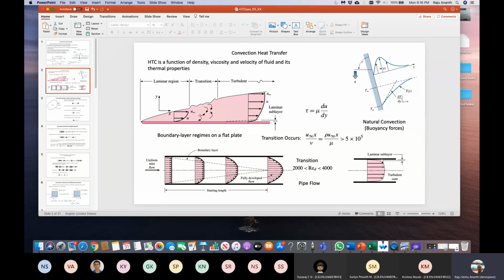Here the slope is a little bit less. So anyway, there's a laminar sublayer here, and this is where a slight increase is, and this is the boundary layer thickness. So this is turbulent. It's not parabolic anymore. It's like the 1/7 law, they call it, but we'll study that a little bit later. This is the velocity profile.